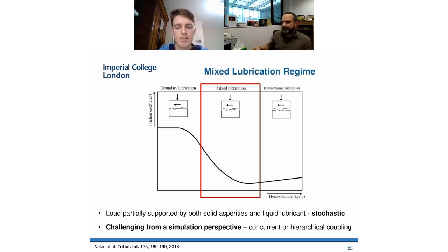So you need essentially mixed lubrication models which tell you where the asperities are, how much asperity contact is occurring under the conditions, what those conditions look like at the local level, and you need lots of information which isn't easy to predict, isn't easy to measure in an experiment, and isn't easy to replicate in a simulation. So essentially what that means is that you have to do some form of coupling to larger scales, whether that be contact mechanics models or Reynolds-like models for fluid flow.